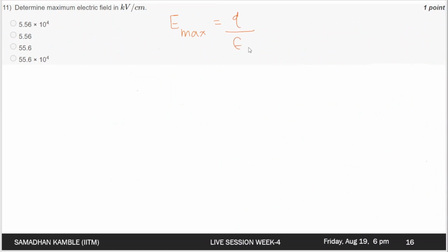Q over epsilon, in our case it is gallium arsenide, times Xn times Nd. So let us consider the N side. You can similarly go to the P side case and you can get the same result. For the silicon case, epsilon is given as 12.88 times 8.85 times 10 to the power minus 14.